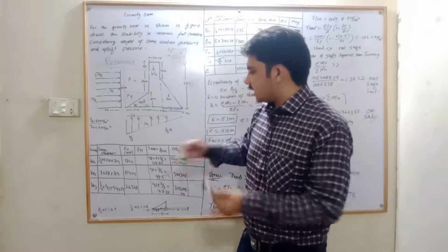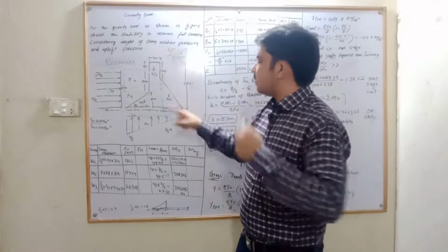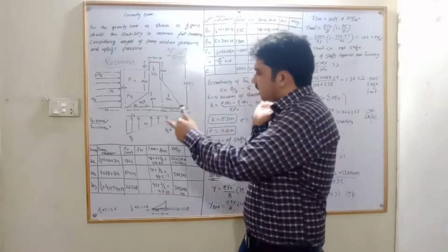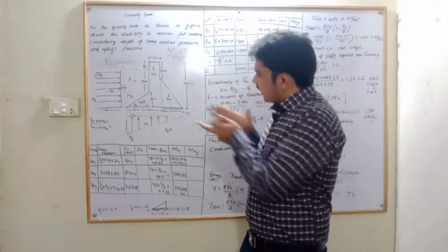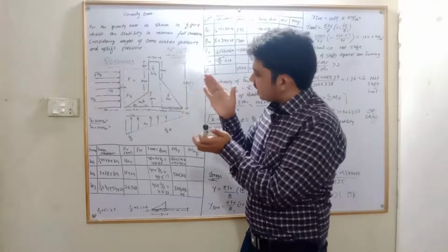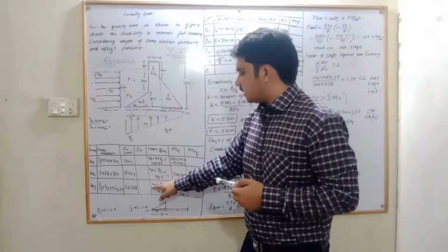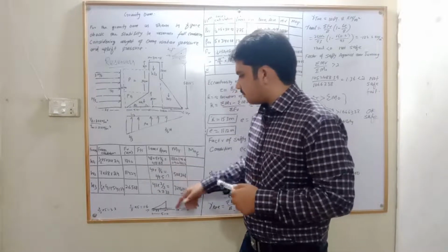So you can get the lever arm. Similarly, you can find the lever arm from this point, which is 41 plus 7 divided by 2. This one is starting from the side which is not 90 degree, the angular side of the triangle, which is less than 90 degree. So you will get 2 divided by 3 multiplied by 41, you will get 27.33. This is the lever arm.